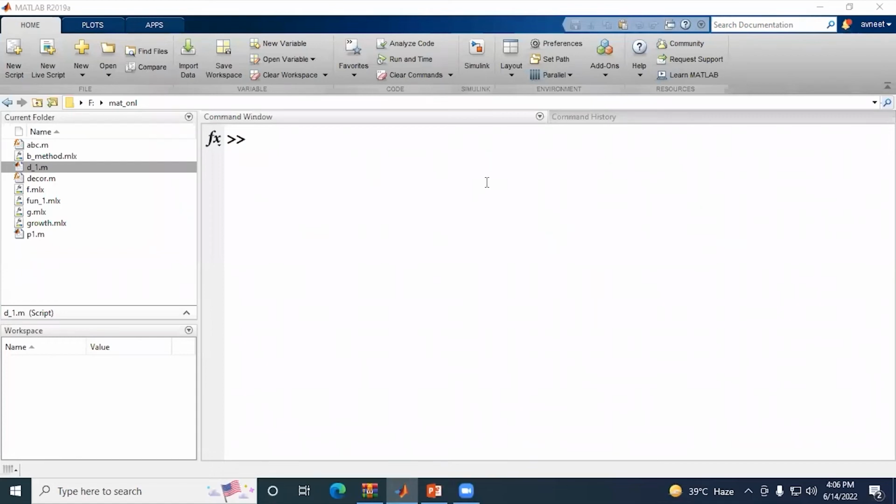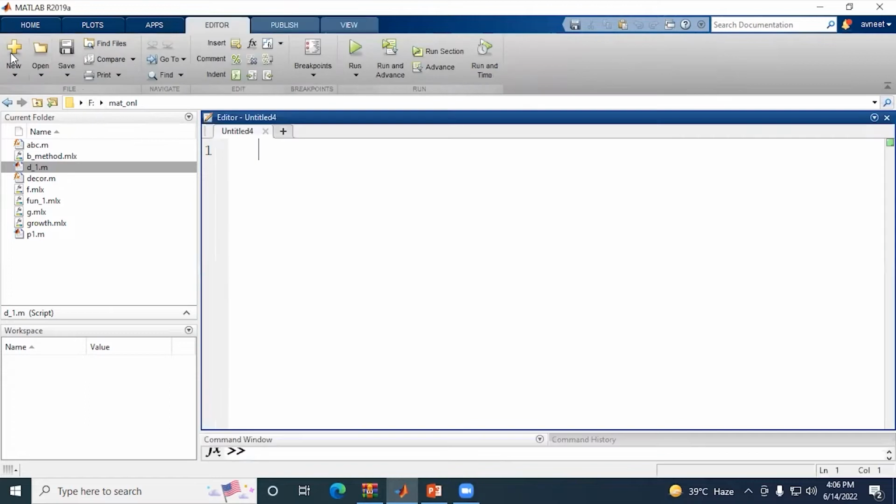Guys, so we were discussing 2D graphics in MATLAB. So this is the time to do some more examples on 2D graphics: how we can create some animations, how we can create some working examples to show how data is changing with time, and actually we are controlling that data with our coding. So let us just start with the animations in MATLAB.